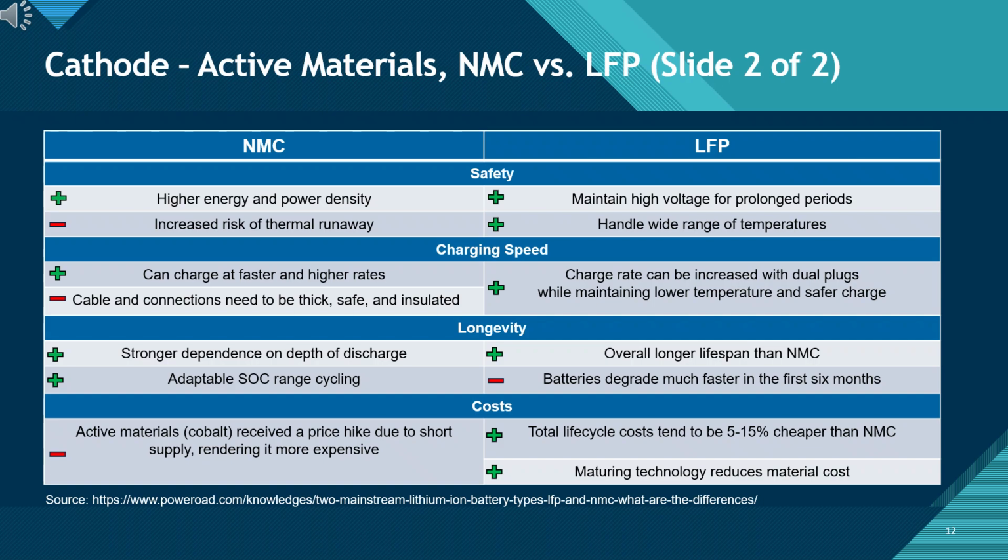In contrast, while NMC offers superior energy density, the safety row reminds us that it has a higher risk of thermal runaway. This means that when you are handling NMC cells on the line, your adherence to safety protocols is even more critical than with LFP. Please keep this table handy as a reference guide. It explains why our customers choose specific cell types for their products.